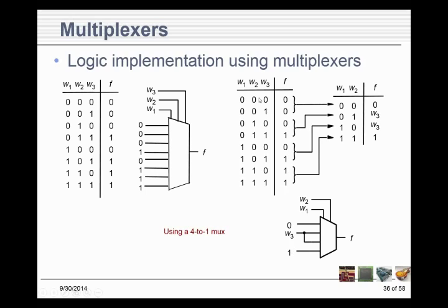So what we've done is we've looked at, now we could choose any two of these, but you've got to be really careful, because you've got to choose 0, 0, 0, 0, right? And then you've got to choose 0, 1, and 0, 1, and then 1, 0, and 1, 0, 1, 1, and 1, 1. So we could do it that way. There are several ways we could have 0 and 0, but it was easiest to just look at these and say these 4 are zeros, so I will use 1 and 2 as my selector inputs, and then I can see what I would get on the output if I connected W3 there. And I can also see exactly what I need from my output and just connect that there.